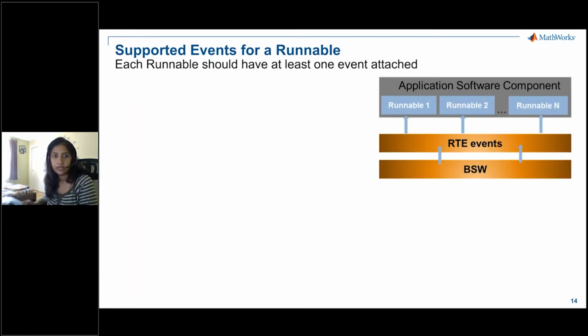So we talked about an application software component in the application layer. Inside that there are multiple runnables, and each runnable should have at least one event attached.